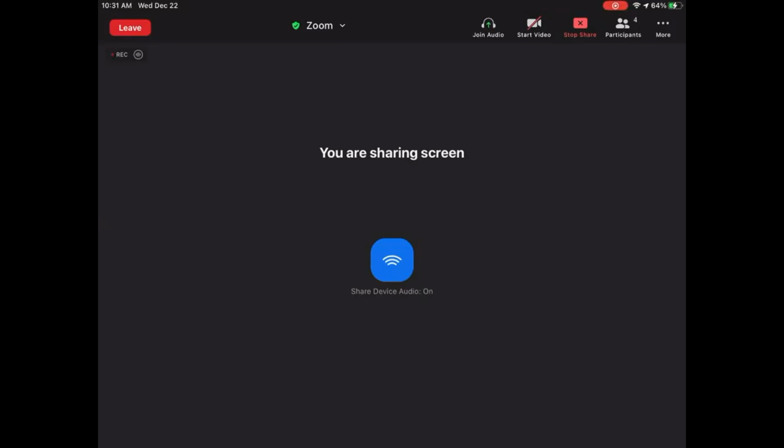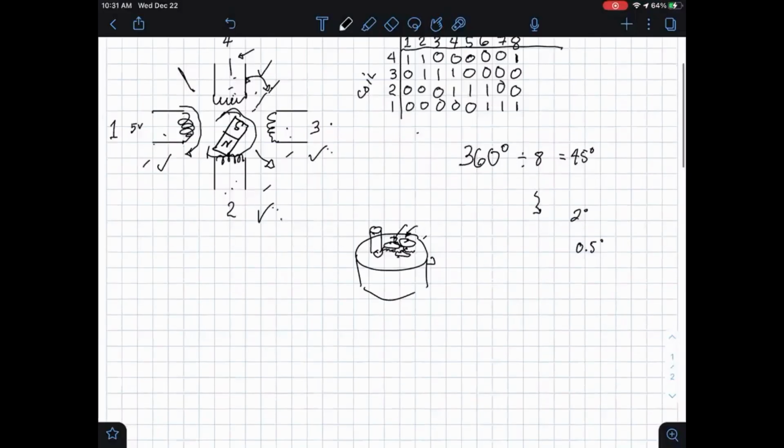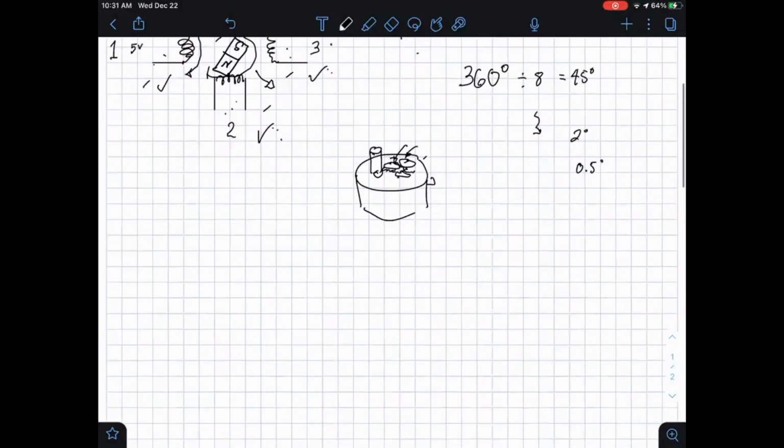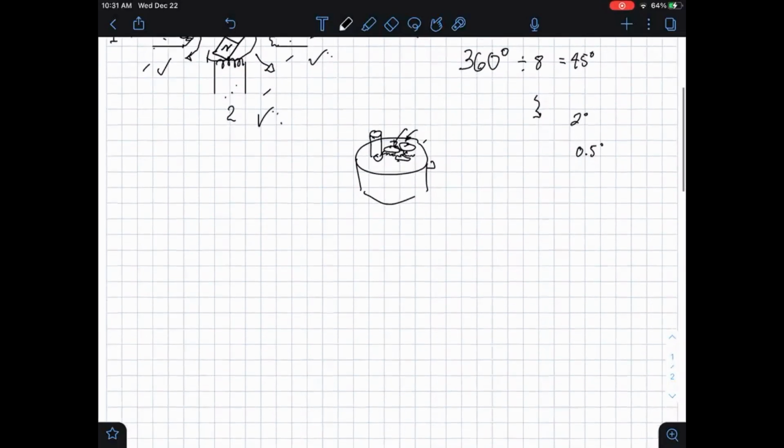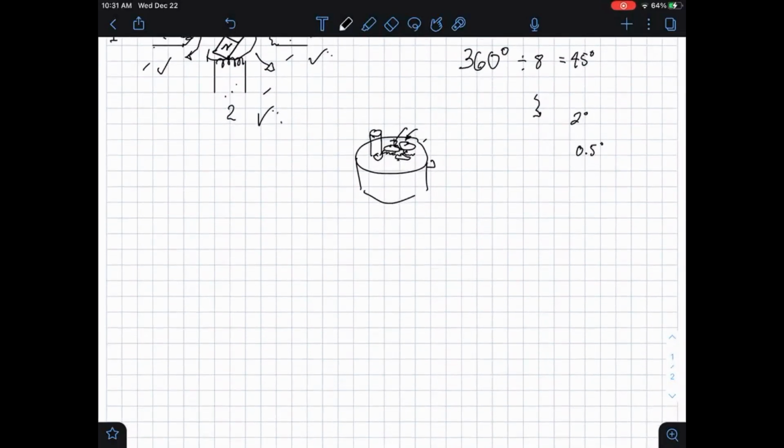So, what do we mean by the digital sunflower? Or rather, the electronic sunflower. Essentially, we have an LDR, and you can detect already by reading the analog voltage in a circuit whether there is sunlight or not, and whether the level of sunlight is high. So imagine attaching this LDR somehow to the shaft of your motor.